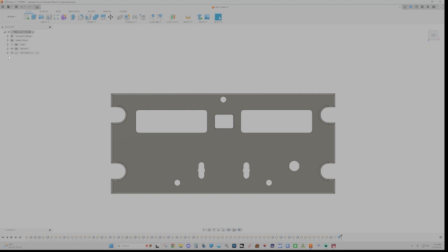Well, we also have, if you remember, we've got the sketch. The sketch is over here, right? So if we go to the sketch and we hover over it, we can see that the sketch is still there. See, all the lettering is still there, right? If we right click on the sketch and then go to export DXF, we come over here, sketch, units, don't change anything, right?